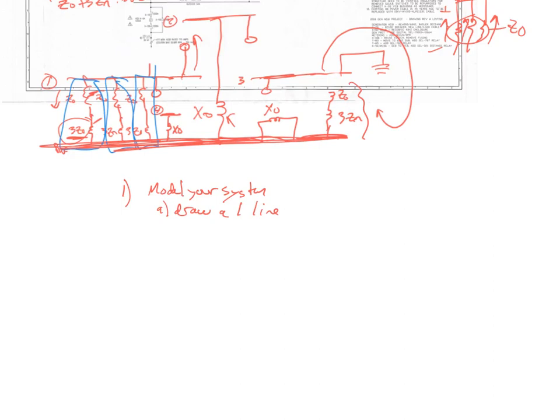Draw one line, right? Step 2 would be calculate your Y bus for your system, right? Which Y bus would you calculate for a three-phase system fault? Three-phase fault.